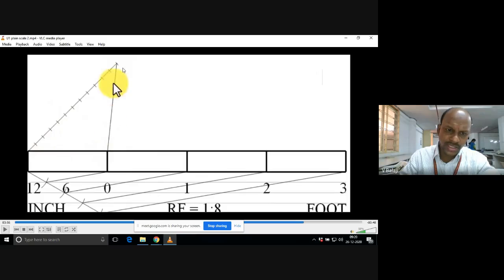So this is the first line, which is the important line. You need to draw with an ordinary scale or a mini drafter scale. Better you use the mini drafter scale. Before that you need to use the mini drafter properly: loosen the knob, okay. Then match this line, draw this line and tighten the mini drafter knob. So see that one of the mini drafter scales is matching to this line, okay. Thereafter simply move the drafter through the various arcs, okay.